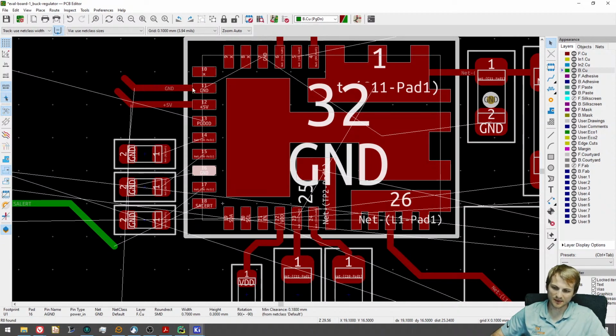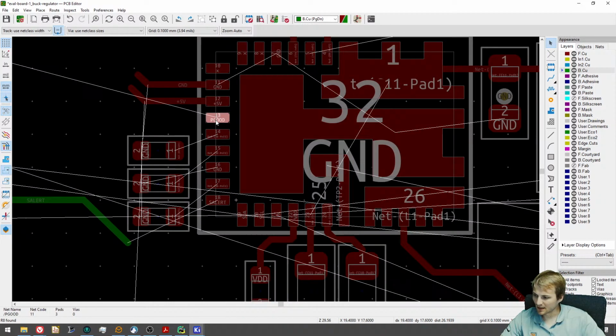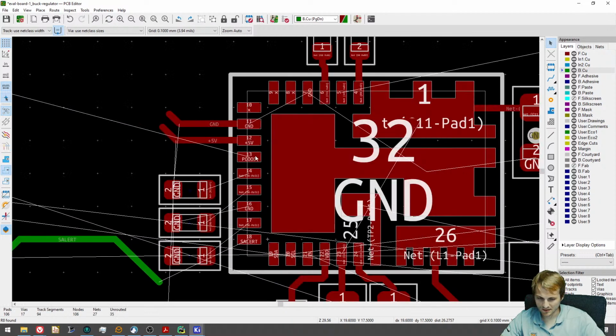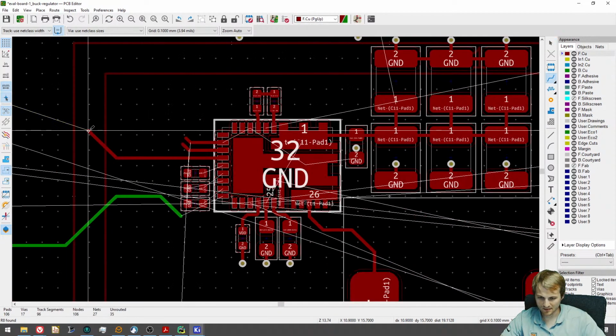So I think they probably kept it over here to have more separation, which is fine. But if this is the analog ground, they easily could have put the two analog pins right next to it. But anyway. Okay, so P good. We'll just go out to the connector.